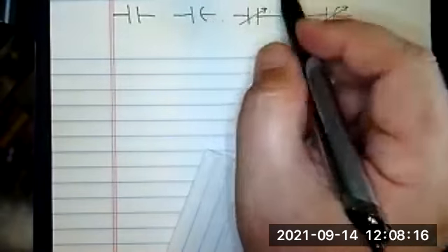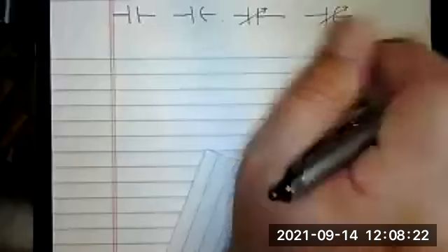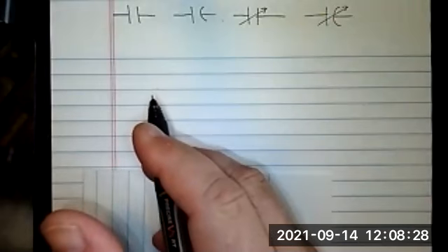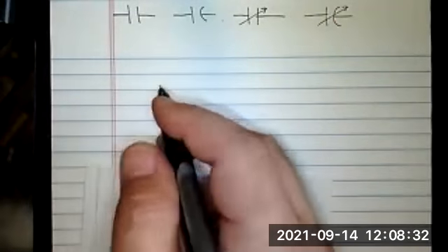The main thing is these three are indicating that, hey, you need to get this type of capacitor. They'll give you the capacitance, and they'll tell you some temperature ranges sometimes, but they'll specifically say a polarity, a polar capacitor, which really fails if you connect it backwards. So that's the difference. What I want to think about is what happens when you put two capacitors in a circuit in series. What happens to you when you put them in parallel? So let me show you something very interesting about that.